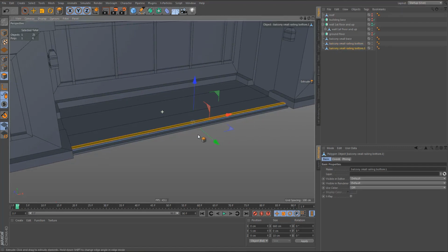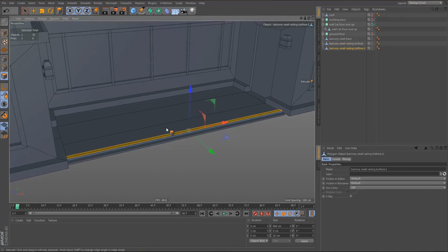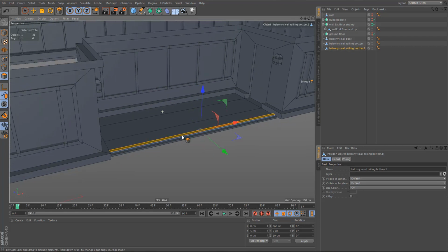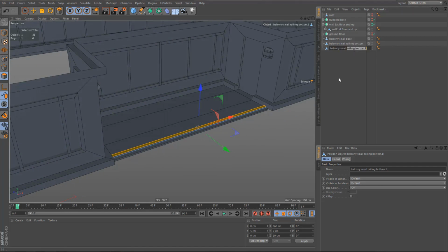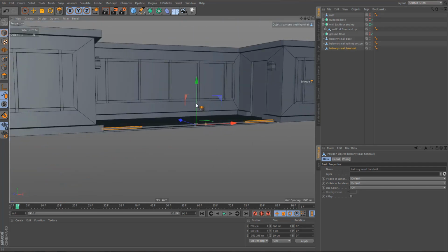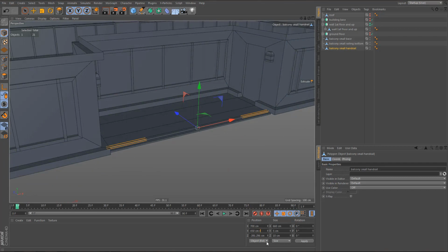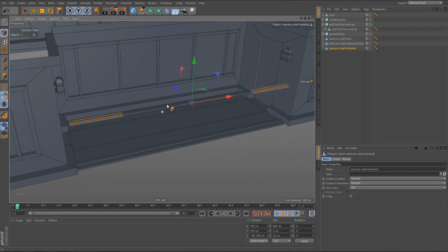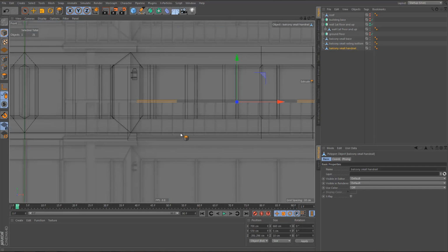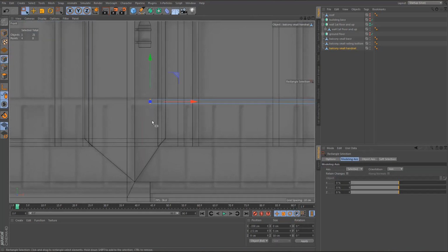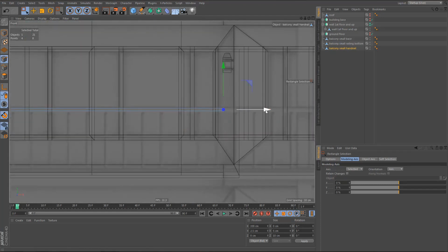And I'll make a copy of this. And the balcony railing will have a height of 130 centimeters, and we'll have 10 for the railing base and 10 for the handrail, so the balusters will have a height of 110. I'll rename this to handrail, go to model mode, and I'm going to move this up plus 120, I think. And we need to make this a little bit wider. I'll just select these points here and snap them to the wall. Same over here.